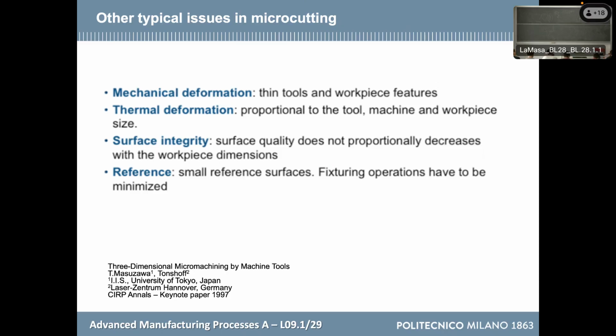In fact, a good rule of thumb in milling is using the biggest tool you can use. So, in other words, if I have to make a thin wall, but I have plenty of space laterally, it is better if I use a big mill. The only point that we have learned today is that the mill can be big, but the cutters should be really small in rounding.